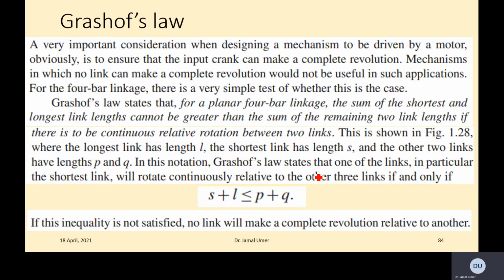The next topic is the application of Grashof's Law. This is one of the very famous laws used for mechanisms. A very important consideration when designing a mechanism to be driven by a motor is to ensure the input crank can make a complete revolution.